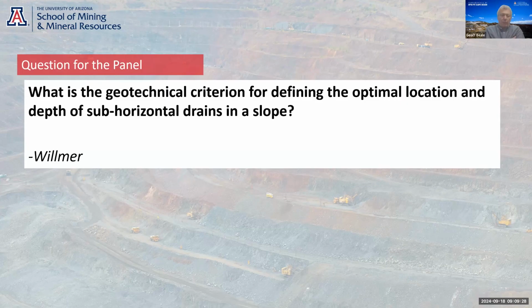So I think one of the things we're really trying to stress now is don't put your piezometers too deep. Don't put your drains too deep. Figure out where your instability is or may be occurring, and focus on that area.